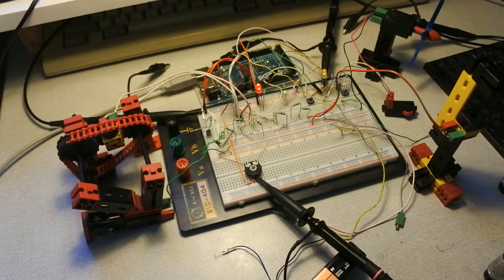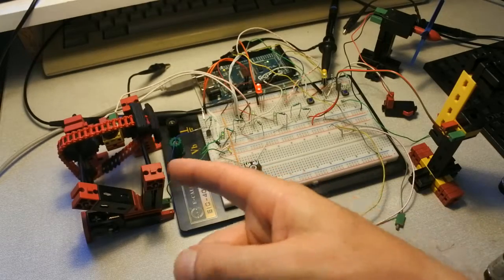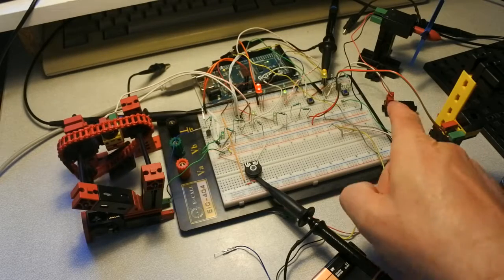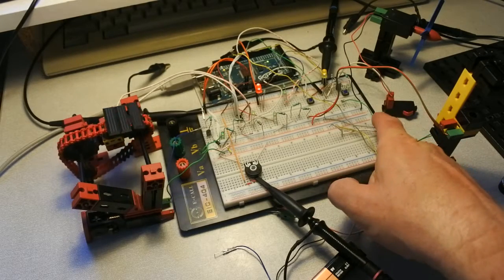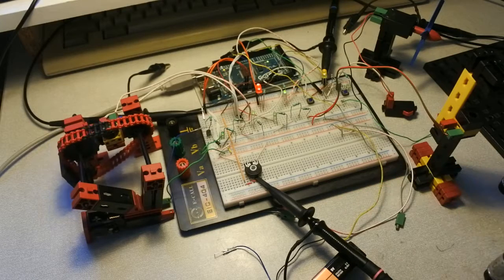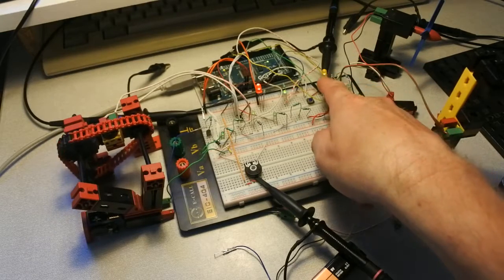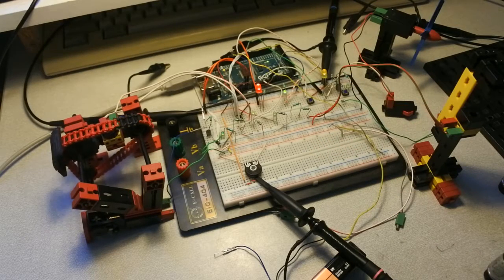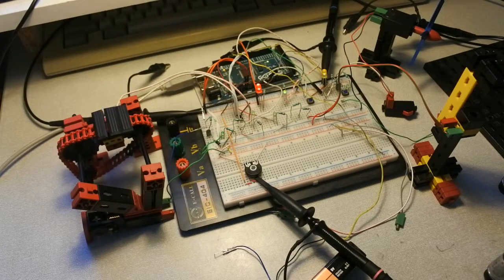Okay, so what is the progress? Well, the progress is that for whatever reason this works again. Rewiring the switch did not work out at all. Changing the pulse width modulated signal on the LED didn't change anything either, because I had hoped that with a value of 512, which is the maximum for an 8-bit controller, the motor would start, but it doesn't.